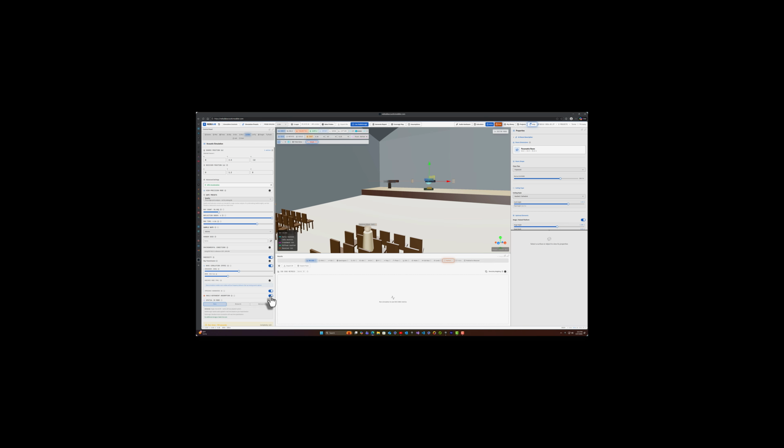Next, let's choose our spatial IR mode, which controls how directional impulse response data is encoded. Since we're using ambisonics, we'll set spatial IR to third-order ambisonics to preserve the highest spatial detail for this demonstration.